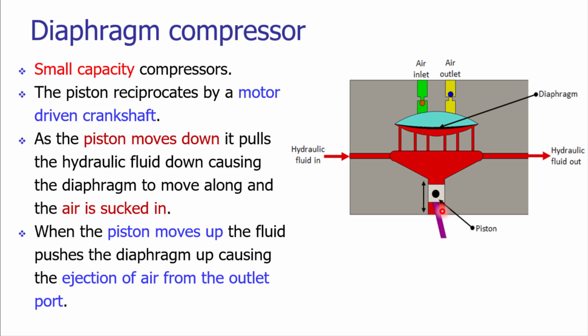The piston is reciprocating and it is driving the hydraulic fluid here. The diaphragm compressors are utilizing the hydraulic energy as well. As the piston moves in downward direction during its return stroke, the hydraulic fluid will be taken inside this cavity, and when the piston is moving in the upward direction, that hydraulic fluid will be pushed into forward direction.